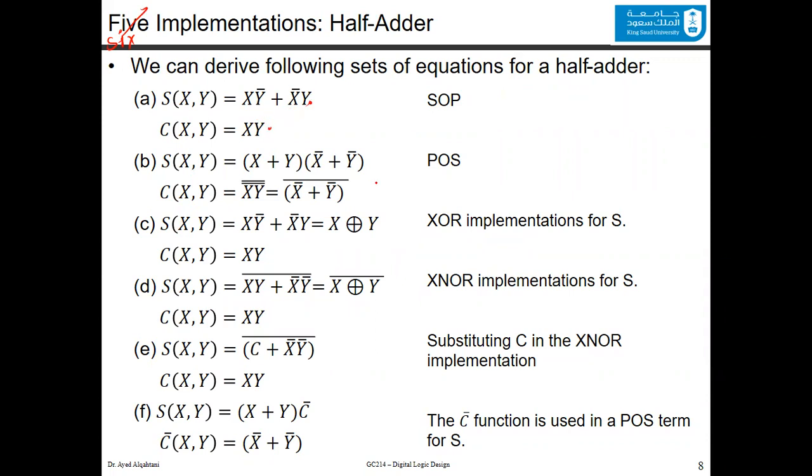If you want to generate the product of sums, you could do it by getting it directly from the Karnaugh map, by looking at the zeros instead of the ones, or simply you will say that the sum is X or Y and the other term.